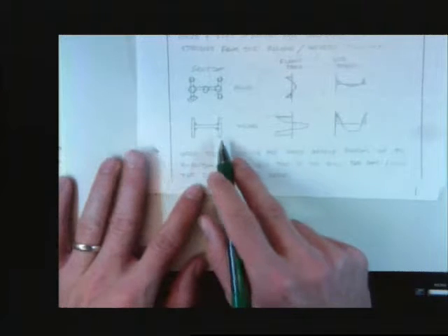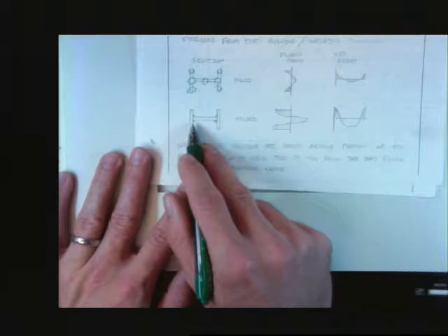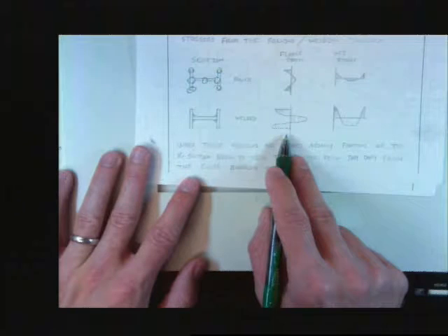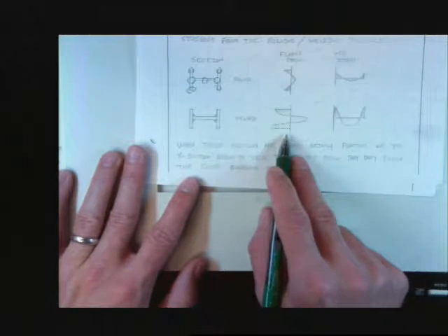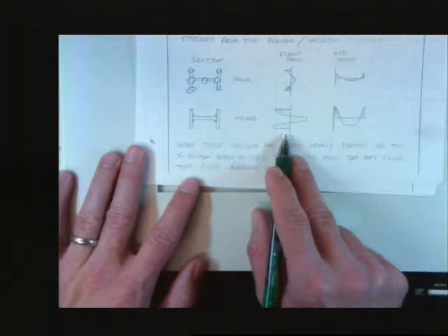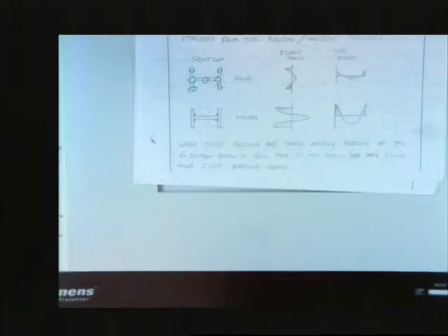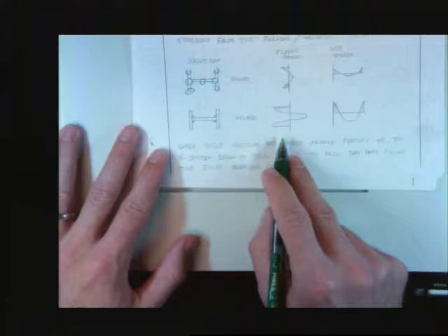And in welded shapes, it's even weirder. Because not only do you have residual stresses from these plates to begin with, but when you do the welds, they totally warp and change what your residual stresses look like. You're like, what? Why have I never thought about these before? Well, if you had me previously from steel, we did talk about them when it comes to columns. But if you haven't, you were cheated, basically. Okay? No. You didn't have to worry much about them, because when it came to failure, they weren't that big of a deal until now. They weren't that big of a deal until it came to columns. But now they've become a big deal.